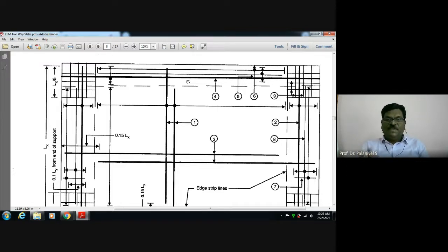Okay, this way it's an art. The architect who draws the drawing should decide, but everything he cannot show. He will simply show something and tell. But the site engineer should take care. He also should be highly knowledgeable in structural design. Accordingly, he has to refer to the drawing. How much area of steel is required? Okay, this much. Whether for 1 meter wide, that much area of steel I am accommodating or not. Then he has to put some pieces of bars there.